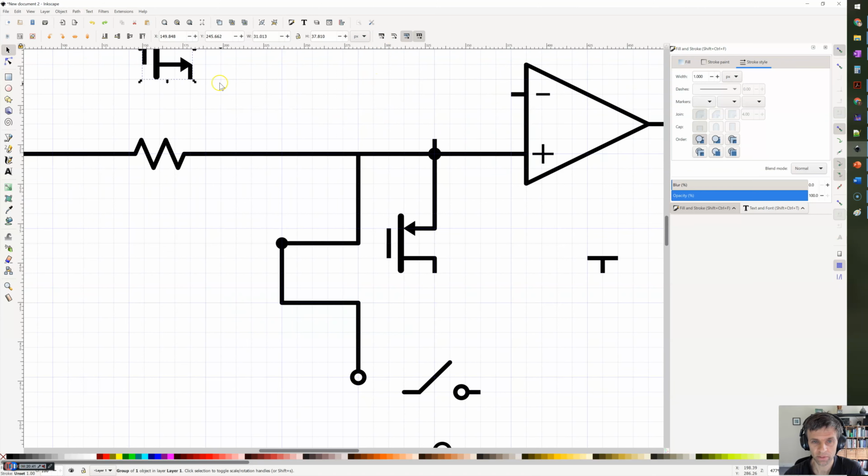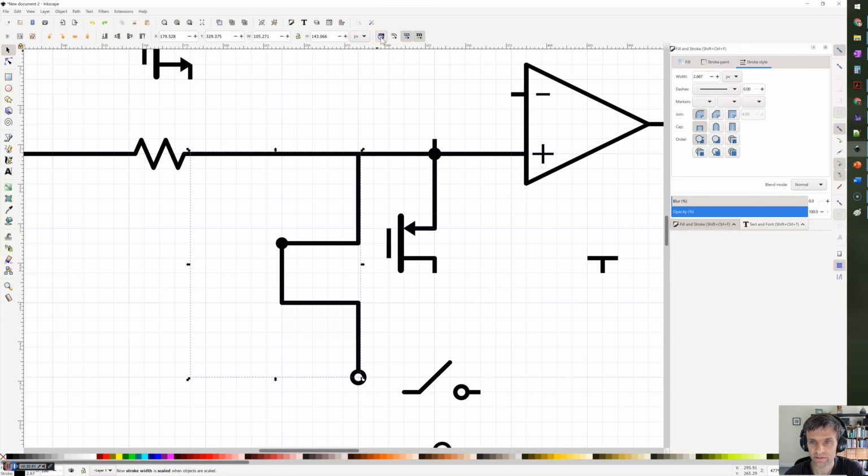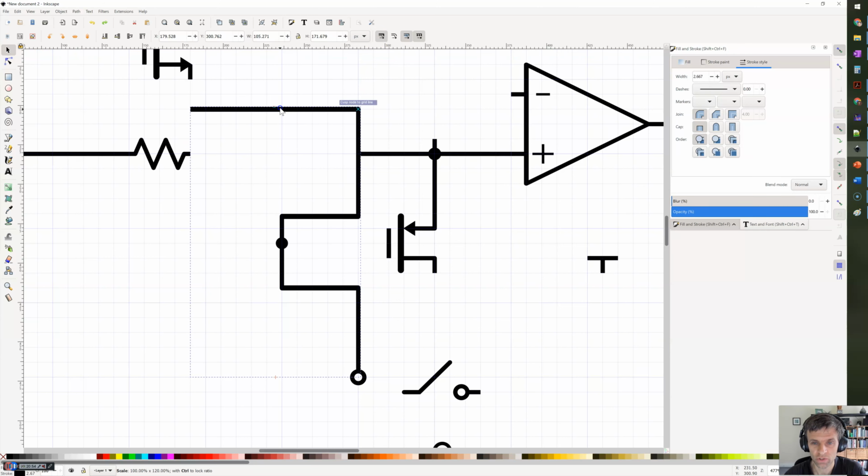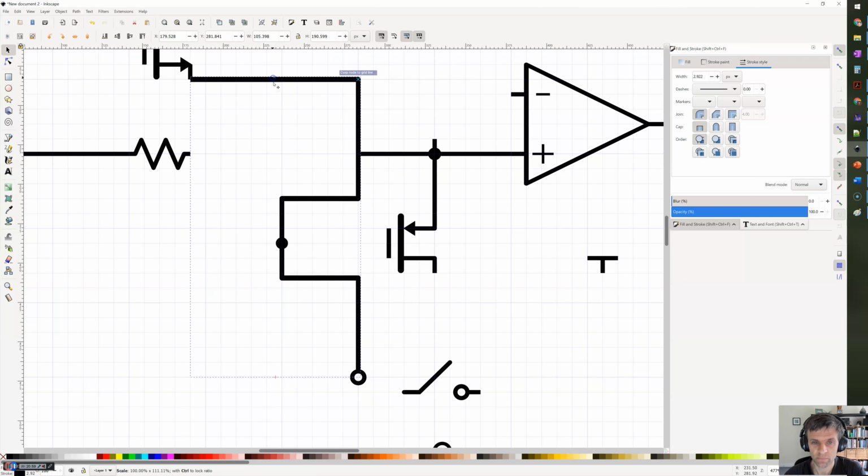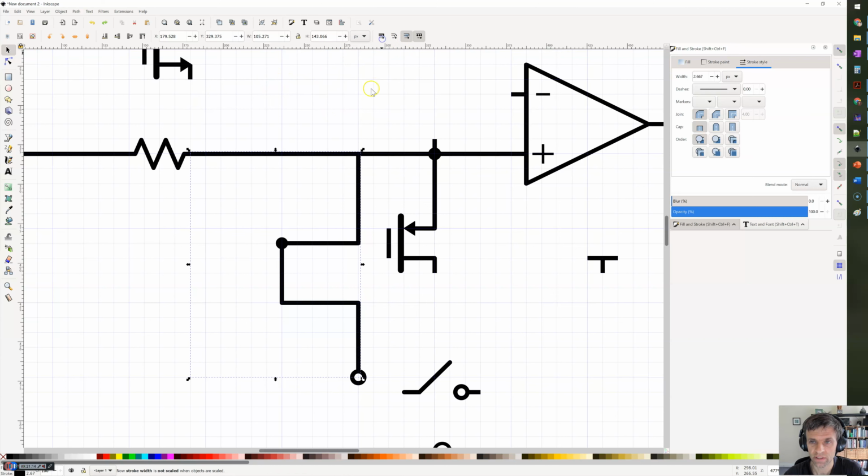You generally want to be really careful in any case about resizing symbols that are already pre-baked in your template, like transistor symbols. But if you have this enabled, you can also get weird behavior like when you stretch a path, right? You'll see the line will actually get fatter because you've stretched this path around. Now some of these path widths are not going to be 2-point width anymore. You can see they're a little fatter than these lines. So that's going to create problems too. So just generally, you want to keep this turned off so that your line widths always stay at 2-point.